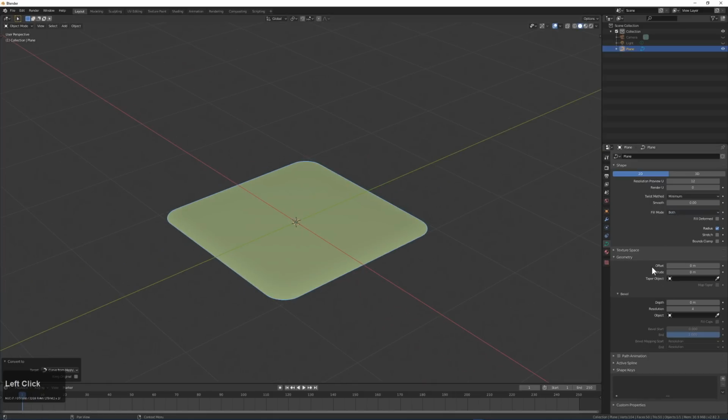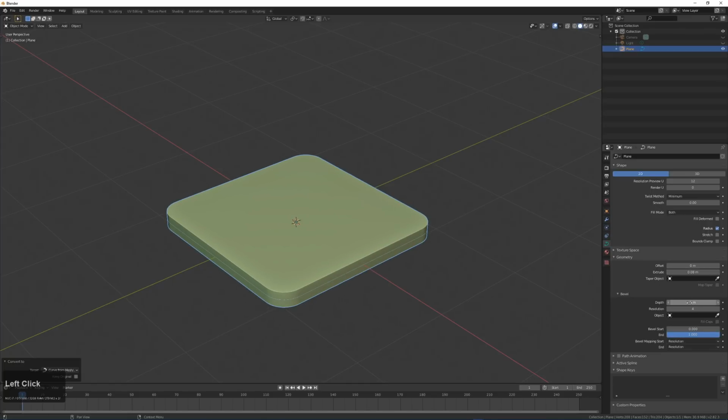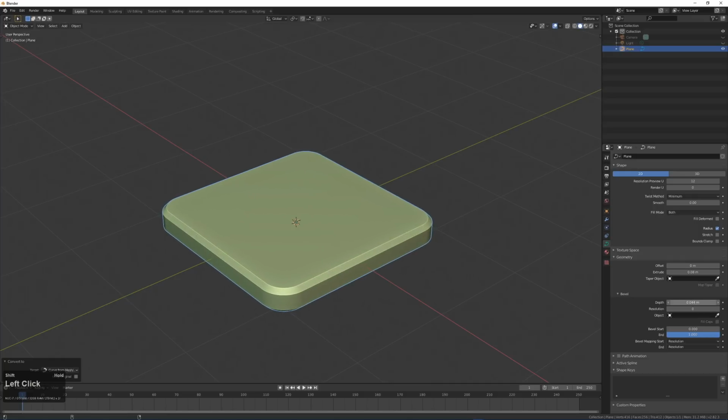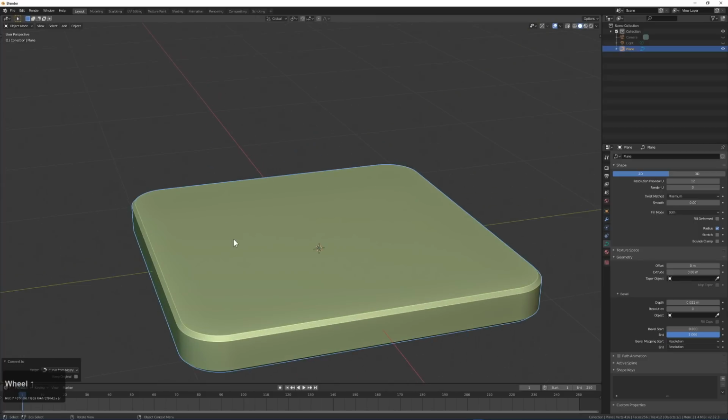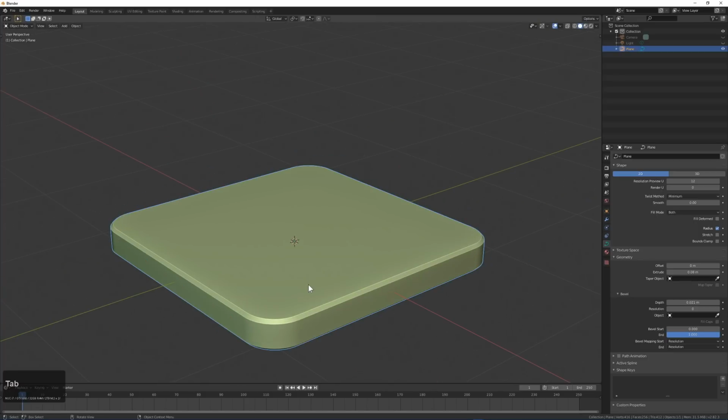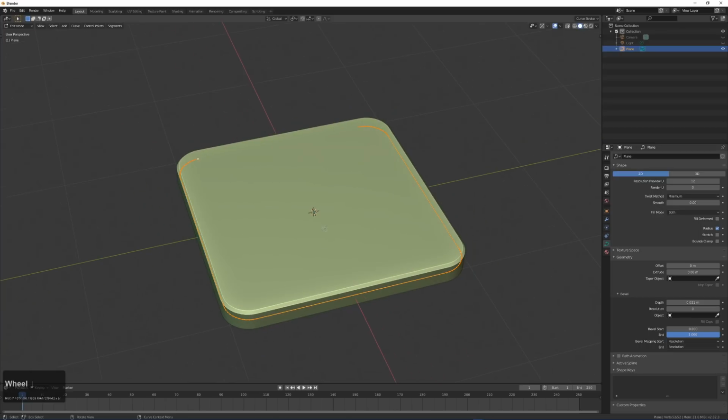And under geometry of the curve panel, we want to adjust the depth. But first we must extrude it. So we want to extrude it, lower the resolution, and then adjust the depth. And now we have this beveled, thickened curve that's rounded on the sides. Even though we can't adjust the sides anymore, it doesn't really matter.